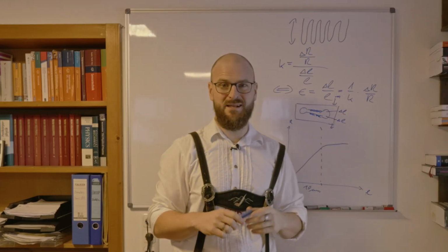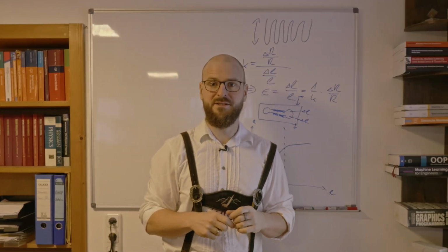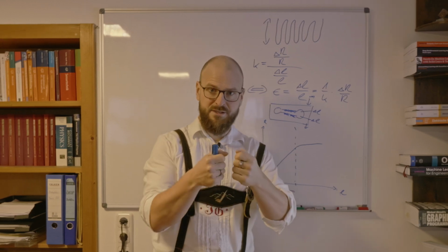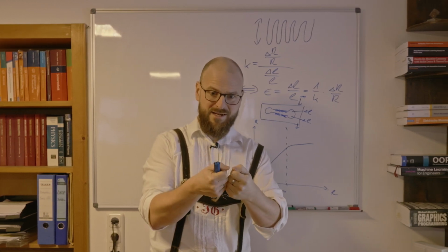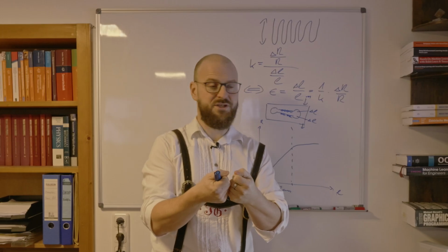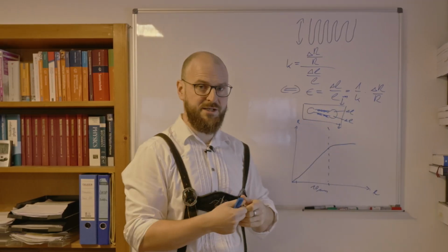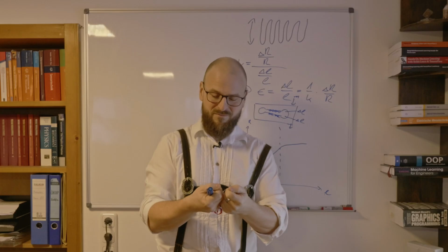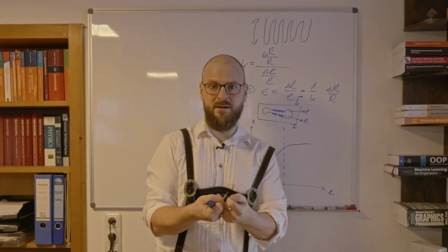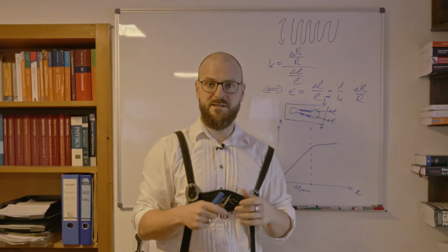That indeed implies another fact about strain gauges. Strain gauges which are kept in an elongated state, which is applicable in the linear range, but are kept very long in that elongated state, will change their resistance over time.